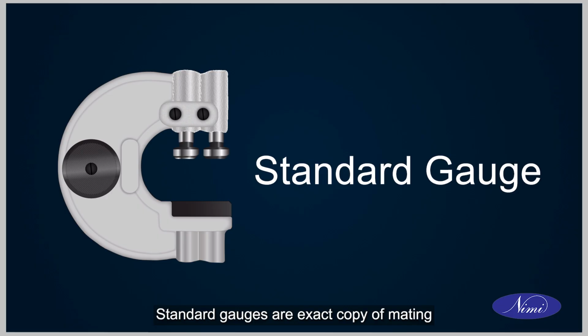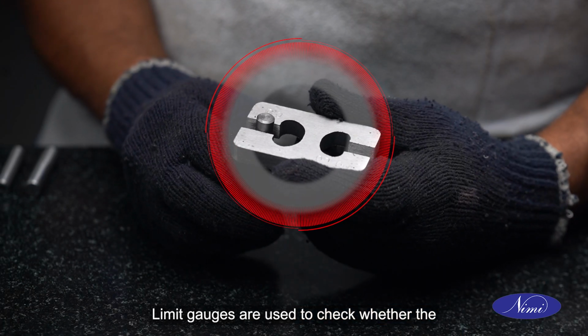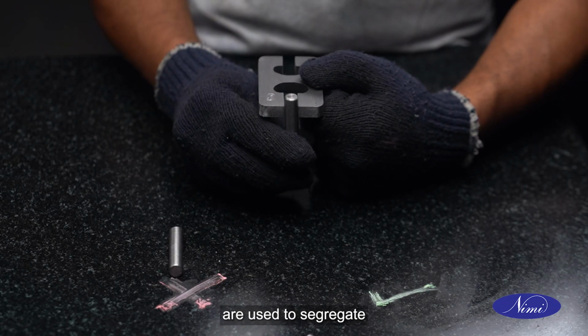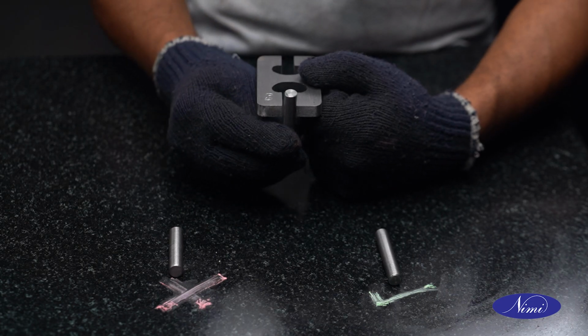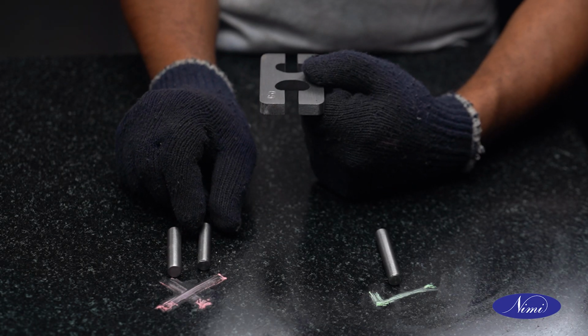Standard gauges are exact copy of mating part of the component to be checked. Limit gauges are used to check whether the inserted part is within the specified limits. The limit gauges are used to segregate acceptable and non-acceptable products in mass production without exact dimensions.